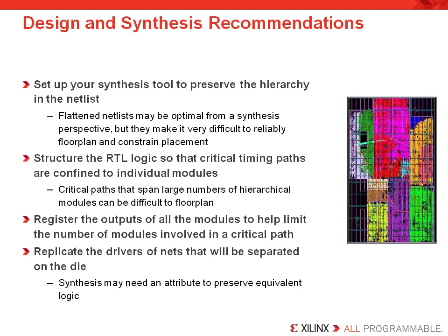If possible, try to structure your RTL logic so that critical timing paths are confined to individual modules. Note that critical paths that span a large number of hierarchical modules can be difficult to floor plan.